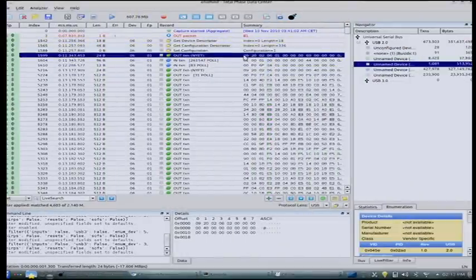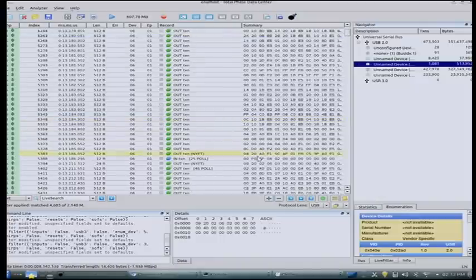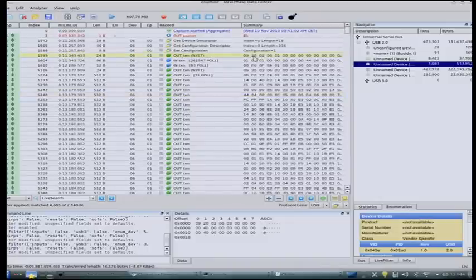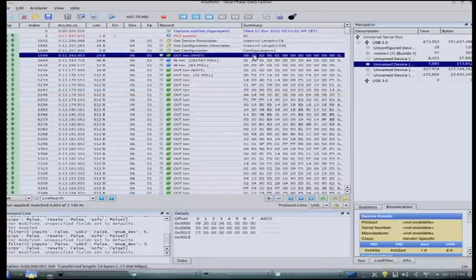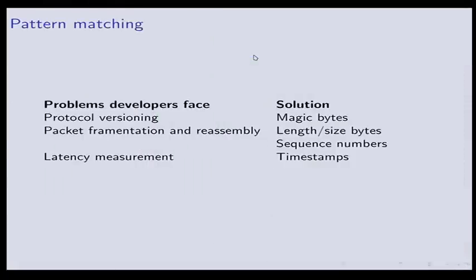So over here, we have the first 4 bytes of this transfer are 09200206, and the same for this one. And if we scroll through, the same for this one. And so this appears it might fit the bill, and even more so, we can think of what these might mean. If we flip little endian, then it reads 06022009, or June 2nd, 2009, which is the day before Project Natal was announced, which was the code name for the Kinect. So we have this magic byte